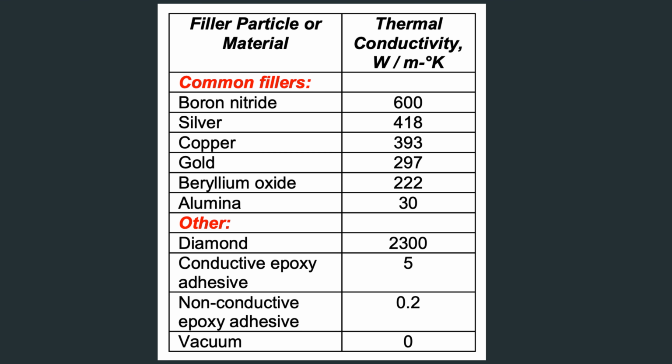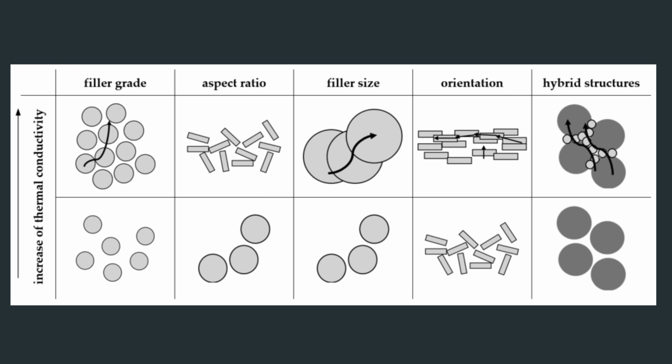They can exist at micro or nanoscale dimensions and take various morphologies, including spheres, flakes, wires, and fibres. The geometry of the filler particles strongly influences thermal conductivity because particle shape affects the contact area between fillers and, therefore, the thermal contact resistance, TCR. Spherical particles generally exhibit point-to-point contacts, whereas flake-shaped fillers can establish surface-to-surface contact, reducing TCR and facilitating more efficient heat transport.